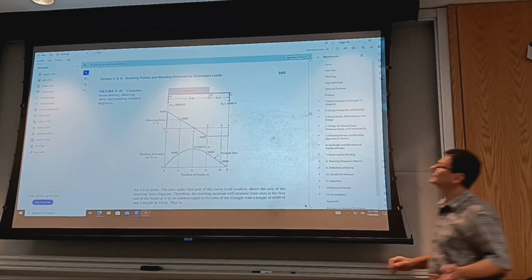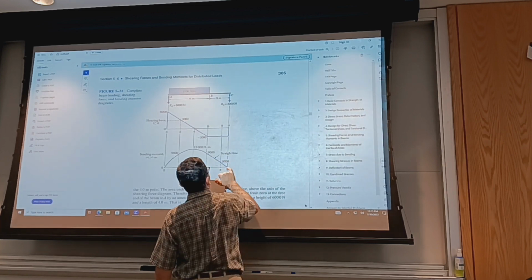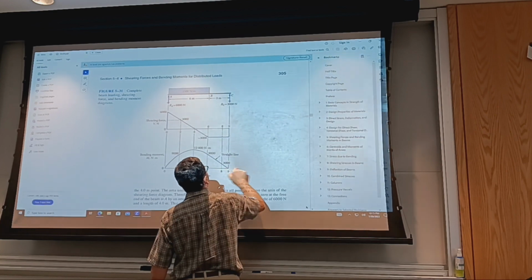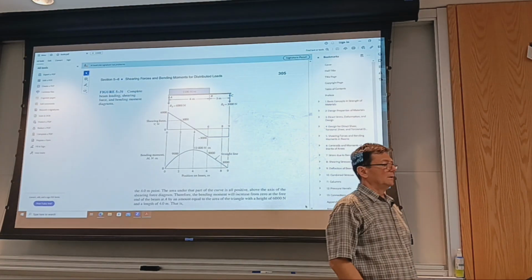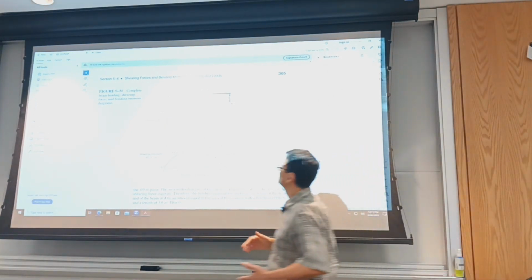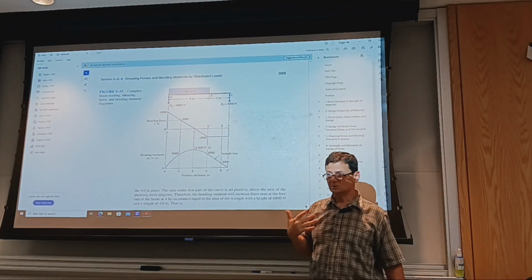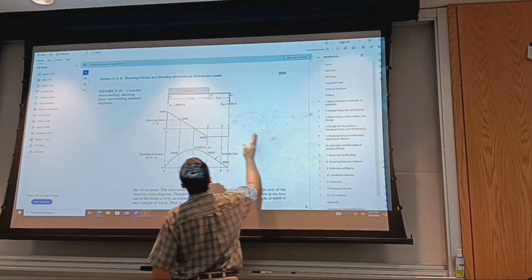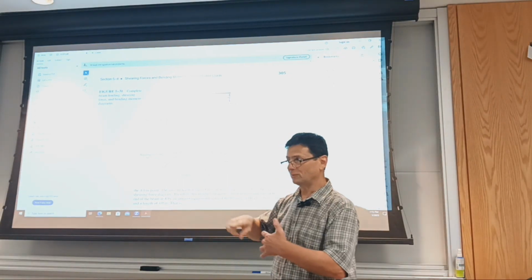Okay, and again, it went to zero because, let's say you continue an inch to the right, there's no load on the beam. So both diagrams went to zero. It doesn't mean that you force them to zero; it means your analysis should confirm this expectation. Sometimes for convenience we go from right to left, but when you go from right to left, signs flip.